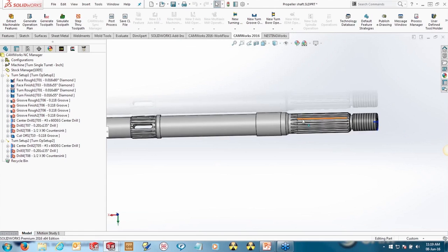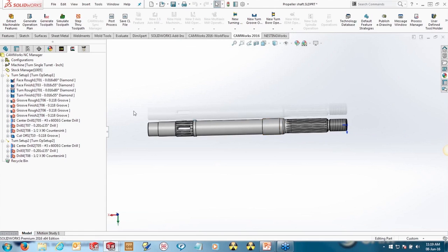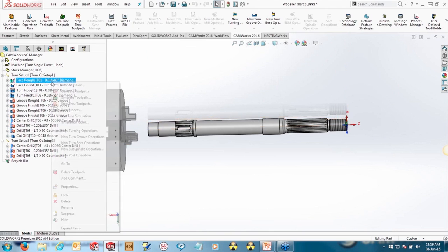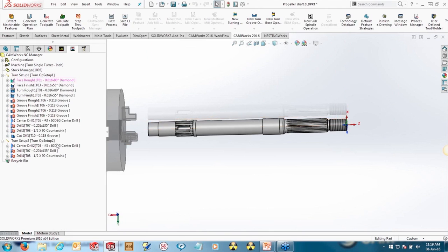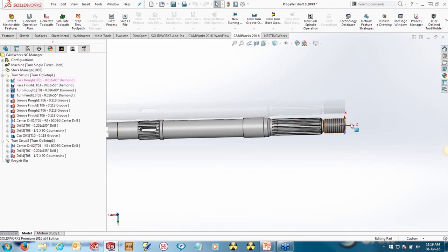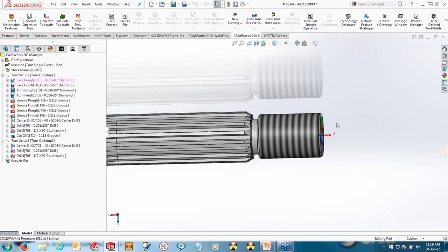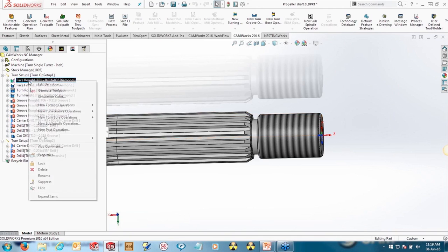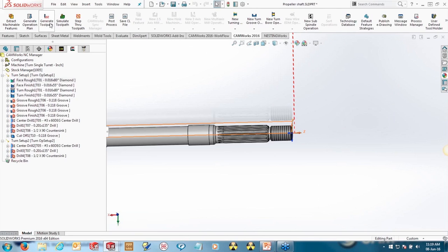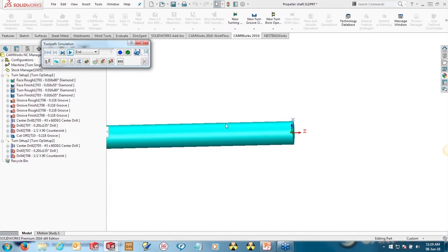Say, for instance, maybe the tool was in the wrong orientation, or it couldn't fit in a particular hole. Then what you would see is something like this. It would actually stay pink here. If I didn't add any material on the end here, it would assume that, hey, there's nothing left to machine, so we wouldn't end up doing a facing operation here, and that's what it would look like. But it basically programmed that file in really 3 clicks.